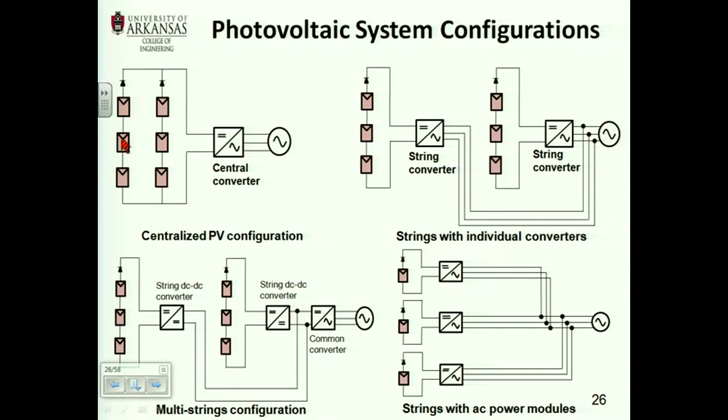The voltage here is going to be lower, so you don't want these three panels that are not shaded to inject current here, right? So that's the reason why you need a diode there. And basically here you get the voltage by connecting in series, you get the current by connecting this in parallel. Each of these is called a string, right?